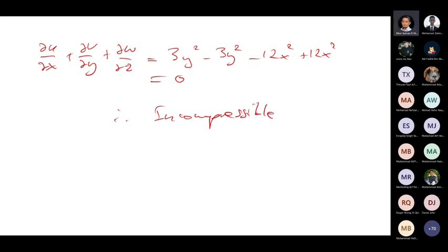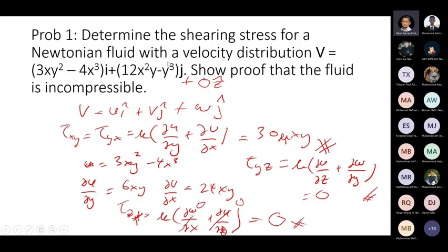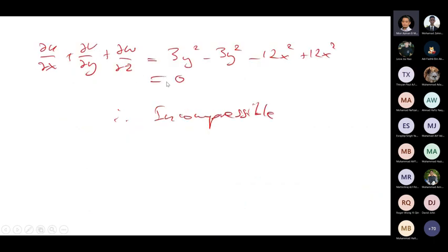And also a steady state, right? It's a steady state because in the equation there are no changes, there's no variable for time. It's just location here, x and y. So there's no t here, so you know that it's a steady state. So it's steady and incompressible.